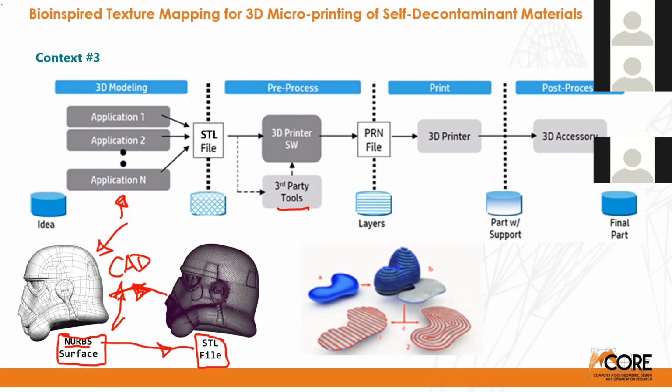For instance, some tools may take the object and reorient it in order to minimize the support material that we see in the printer, because the printer prints layer by layer, putting the object itself and also the support material, so that structures that are hanging in the air will not fall down when you print the layer in material that is not dry yet.